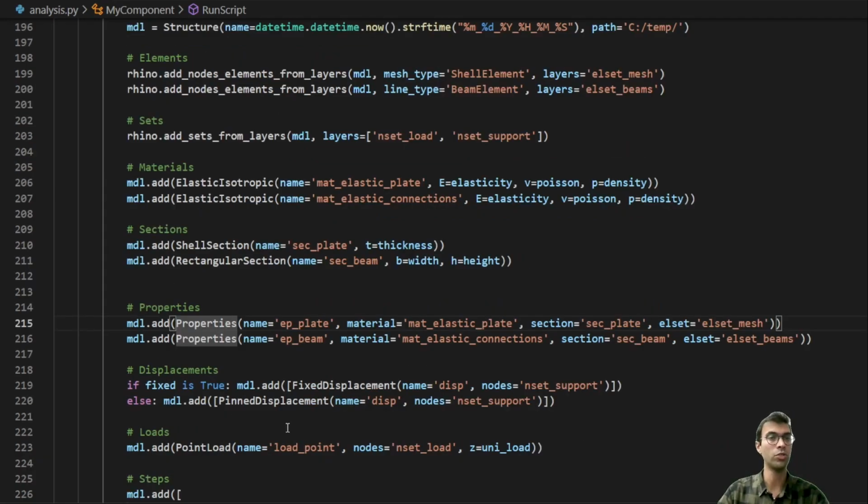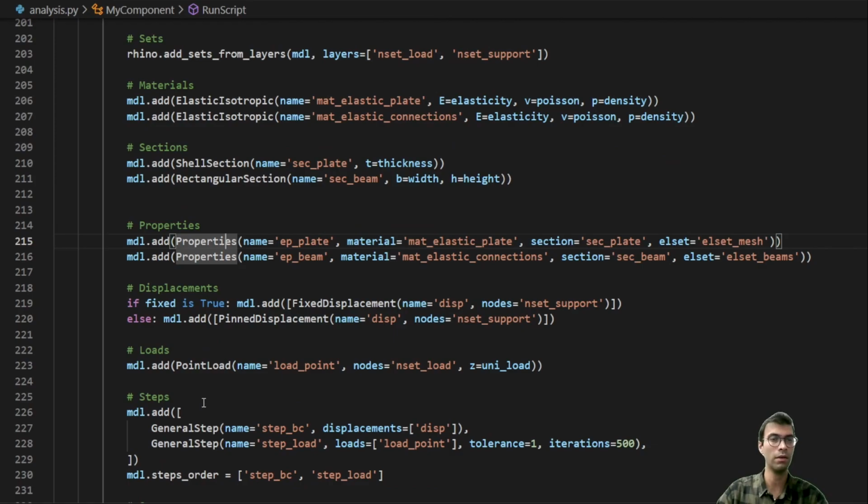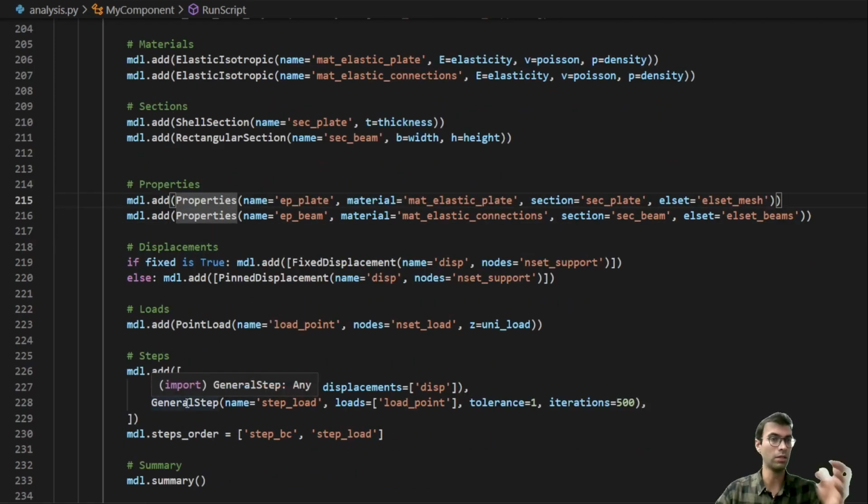Okay, now by having both geometrical and mechanical properties of shells and connections, we assign those two categories into already defined layers. And then, given that our support conditions can be either fixed or pinned, we assign each of these properties to the associated nodes that we've already defined. We assign point loads by using the point load command in Compas FEA, which automatically assigns the direction and also the amount of load per node.